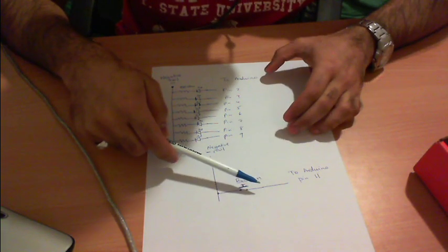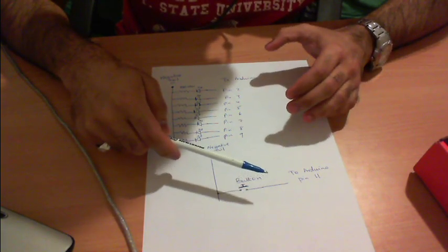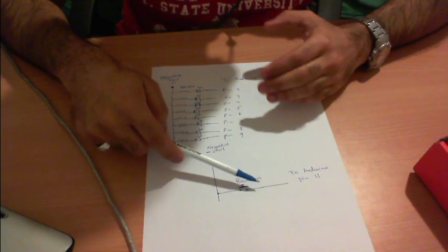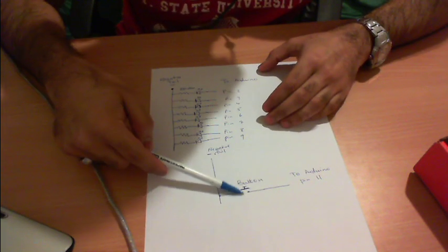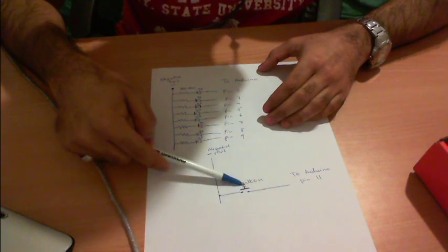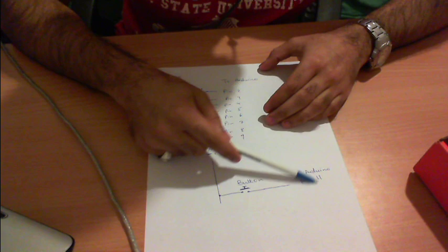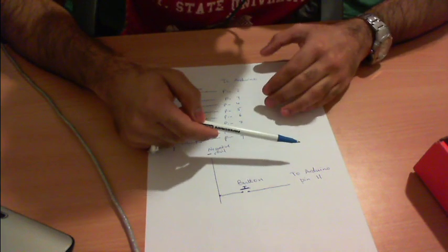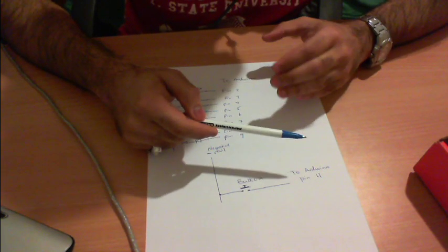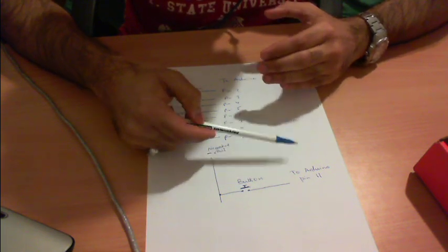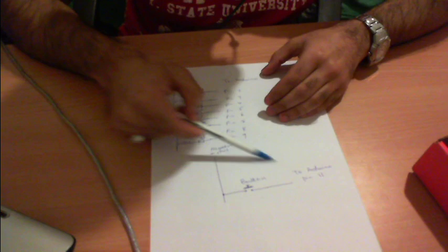Now if you look at this diagram, you might think that this should work, but with the Arduino, it generally senses if a pin is high or low, but what's going to happen with this sort of circuit is that in this state where the button is not pressed, the voltage on this pin 11 is going to fluctuate and vary. So the Arduino will not get a constant high or low value on pin 11 in this situation.